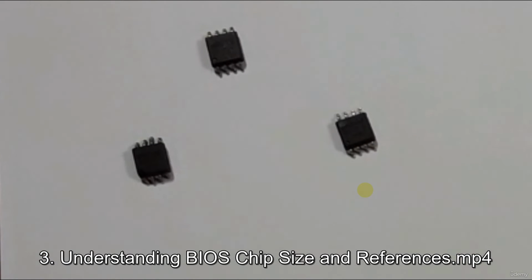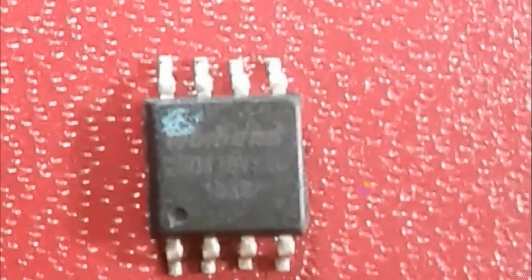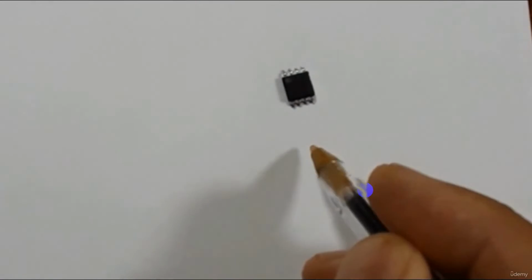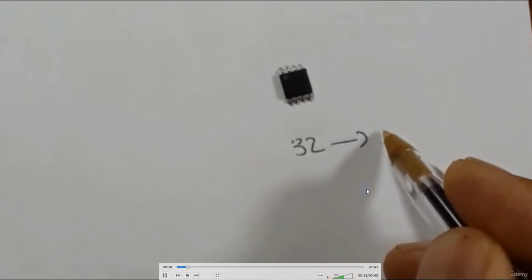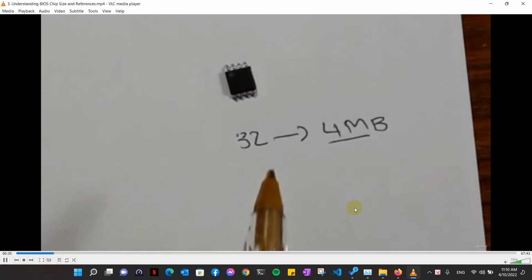In this lecture, I'm going to show you all about the BIOS sizes. So let's check this BIOS, for example. As you can see, we have 25Q32 BVS 32. Okay, so in this BIOS we have 32, as you can see. 32 means 4 megabytes. The size of this BIOS is 4 megabytes. I will show you how I calculate.